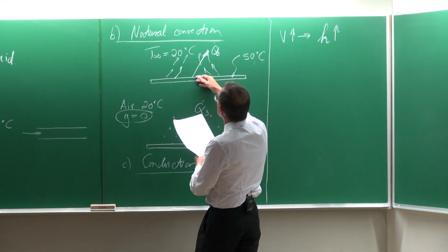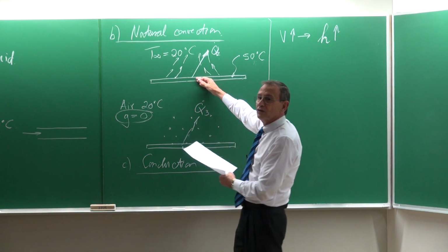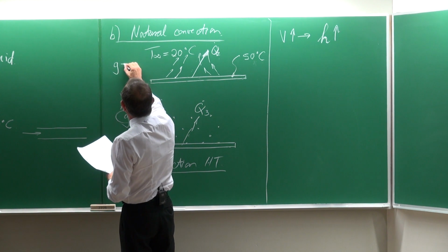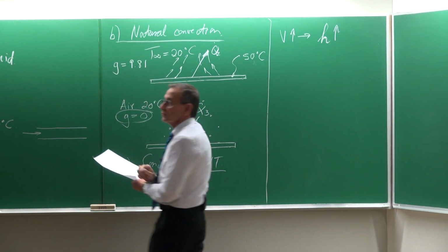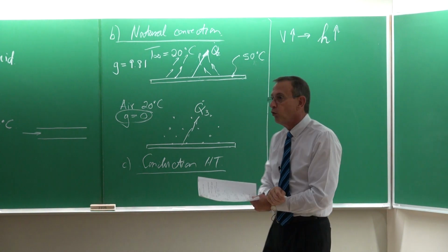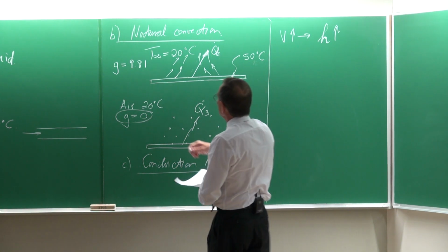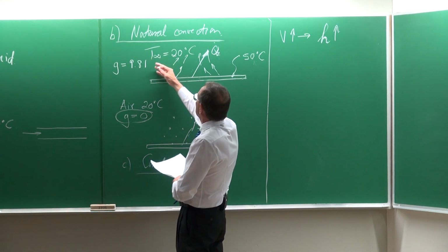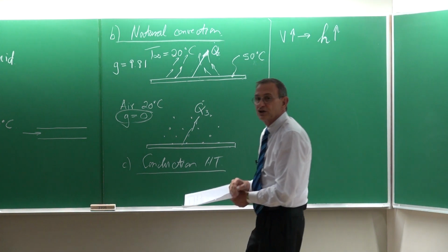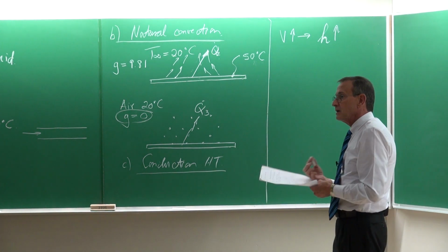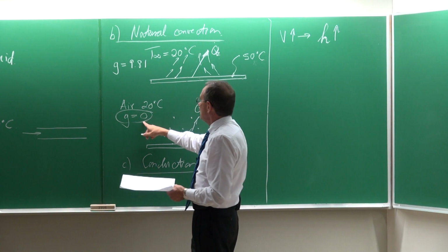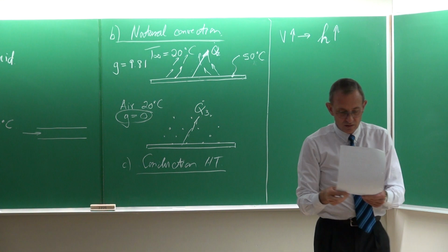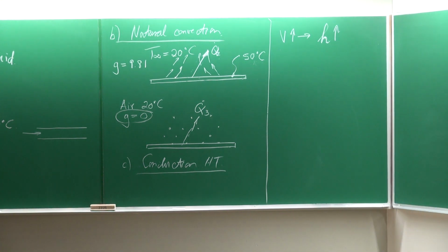With natural convection, you do not have any control over it, except if you can change gravity. If you increase the gravity force to 20 or 30 or something like that, maybe on other planets and places like that, then the natural convection will increase. However, if we take the gravity away, then there's no buoyancy force, and the heat transfer will be by conduction only.